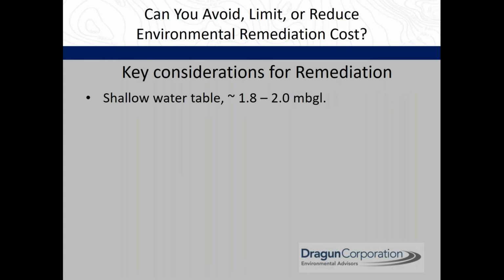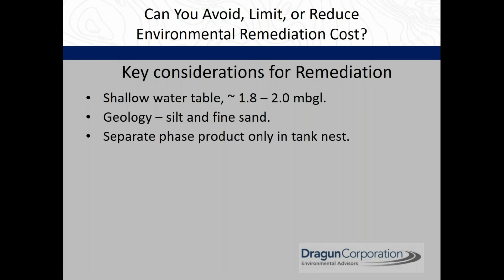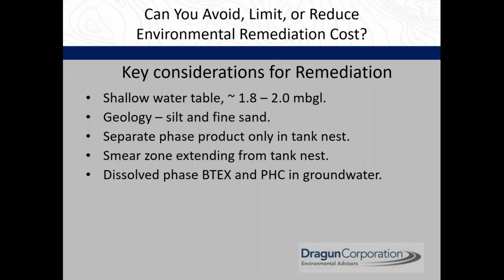So the key considerations we talked about: we had the shallow water table, a sandy soil, the product was only around the tank nest. We had a smear zone around the tank nest and a little bit outside of that tank nest. We understood what hydrocarbons were present.